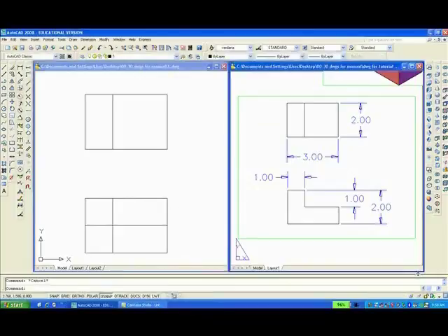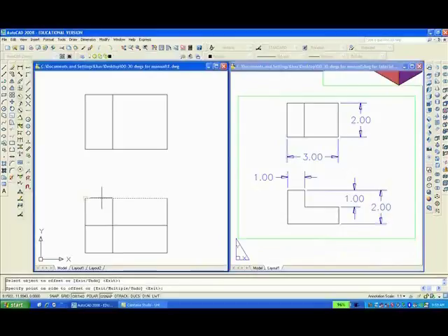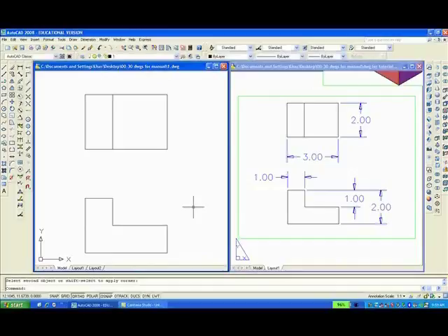Next, you will want to draw a fillet with a radius of 0. F enter, R enter, make sure 0 is shown, hit enter. Now you can select your fillet. You can select 2 lines. Try it again. F enter. I'll select these 2 lines to clean up the intersection. Hit the space bar, clean these 2 lines. Again, these 2 lines. And you can see that the simple 2D drawing form is complete.